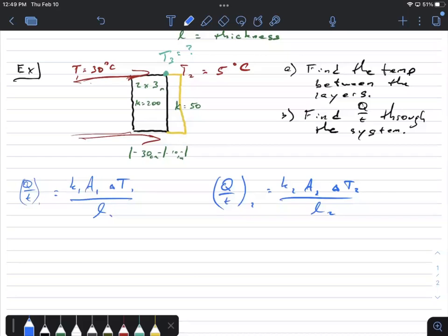Well, that doesn't make sense either, because let's say you had two layers that are exactly the same. You have a wall, and then you put a second wall right behind it. Well, the heat transfer rate of the first one, let's say, is 200. The heat transfer rate for the second one is also 200. But if I put them together and what I'm supposed to do is subtract them, then I'm saying that the heat transfer rate through two walls is 0. But that doesn't make sense, because two walls can be thought of as one wall that's just twice as thick. And of course, I could do that calculation and get a number for that. So obviously, there's something weird.